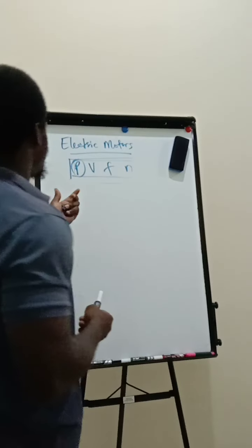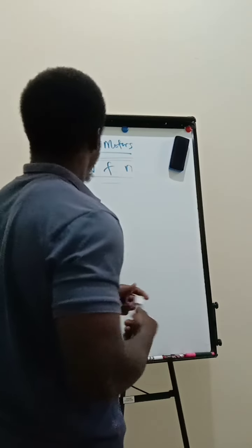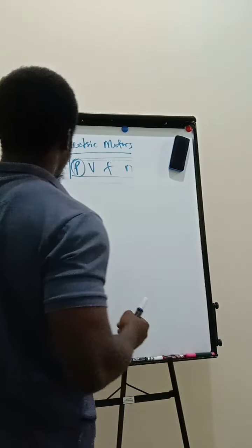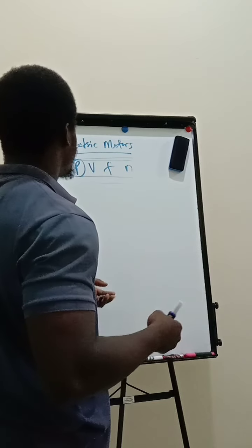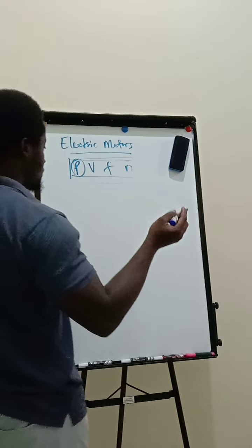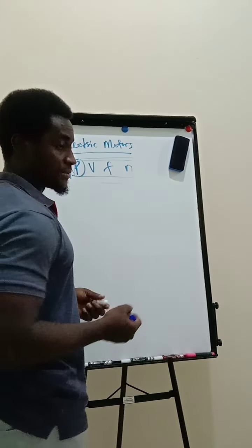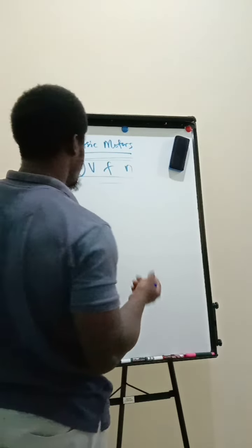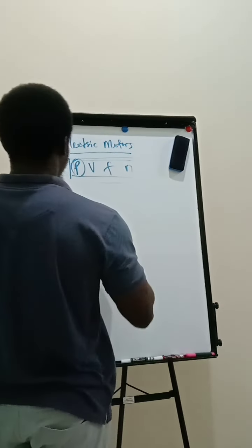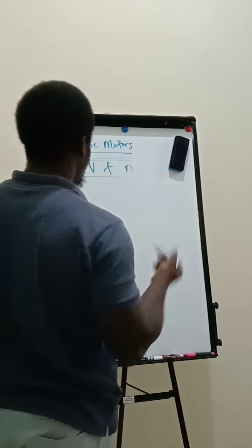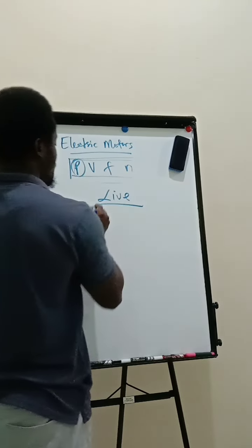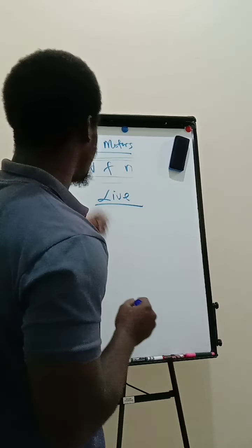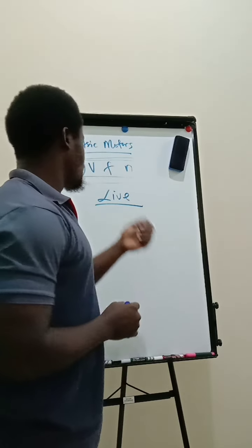Okay. Next we'll be talking about how we test the electric motor on live, because we already discussed the dead test, which is the continuity test and the insulation resistance test or the mega test. These were successfully carried out and we passed. So we'll now move to the live test, which is giving power to the electric motor. After identifying the starting method, we start it.